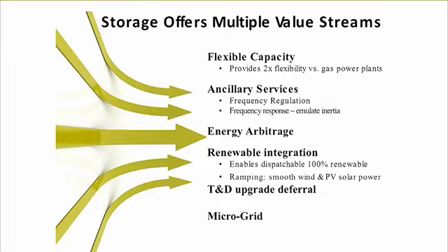Basically, besides supplying energy, the system has to be reliable and has to be able to work even before renewables were brought onto the grid, so contingencies and so on. So the first point here is flexible capacity. Flexible capacity might traditionally be served by gas generation. One could note that if one has electrical energy storage with a battery, or with a flywheel also, one has the capability of regulation up and regulation down in terms of capacity.